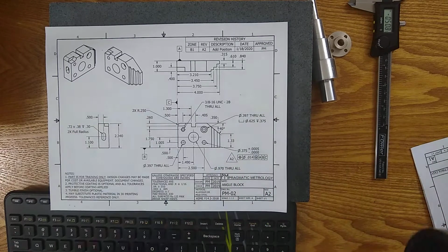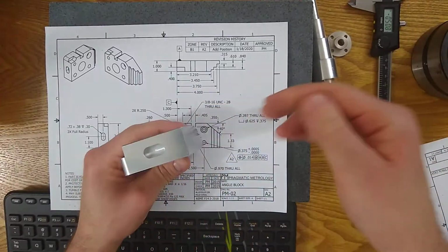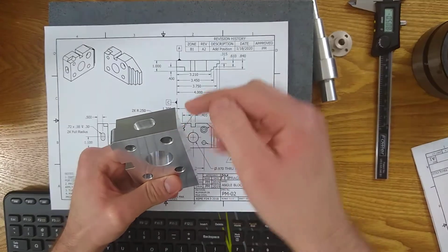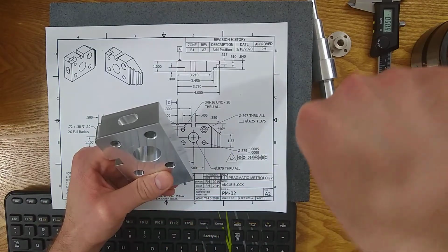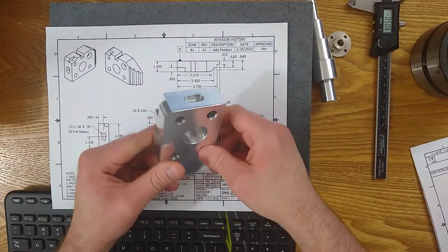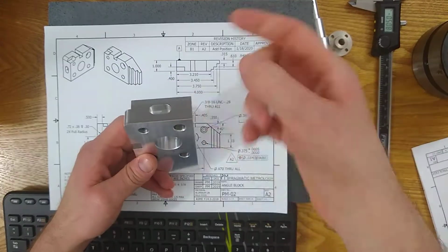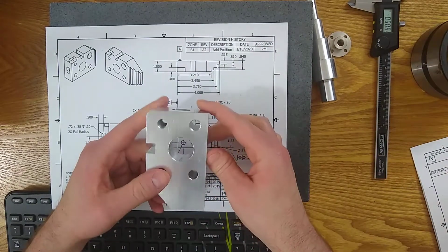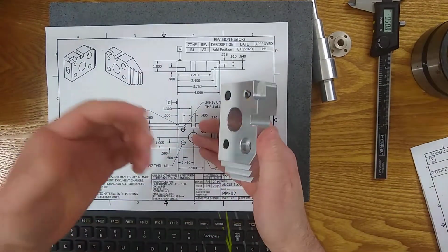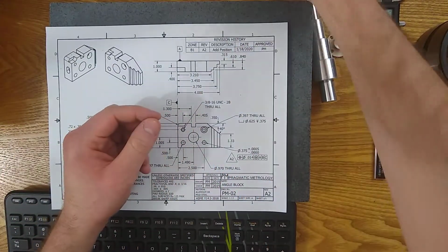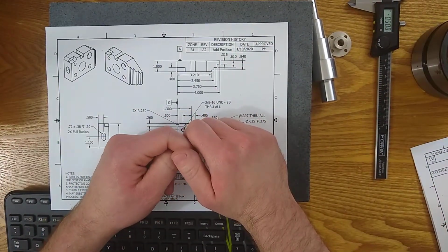And even in a solid billet, if you tried to drill all the way through this 4 inches, you start up here and end up on the back side, it might still walk through the material and bend, because as sharp and as rigid as drill bits are, they can still bend a little bit and still cut, so you won't notice any problems. Machining metal parts is the industry I've been in, but other industries probably see the same problem. So check both ends when you're looking for walking.